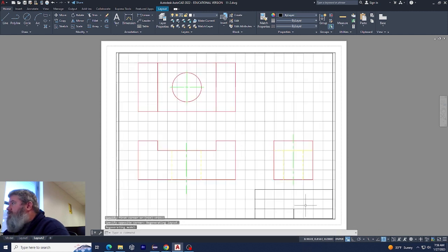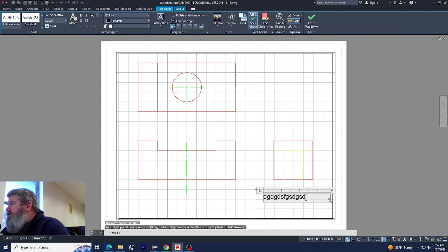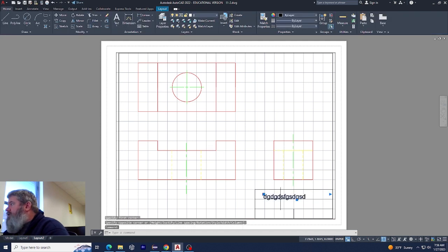Okay, there you see is my paper space. I would label the text in here. So I would put it here, draw it, and write whatever I want to write in that space right there. And of course, you can move it around to fit in there accurately. So you would do that in your paper space, not in your model space, okay? So that's what that's saying.